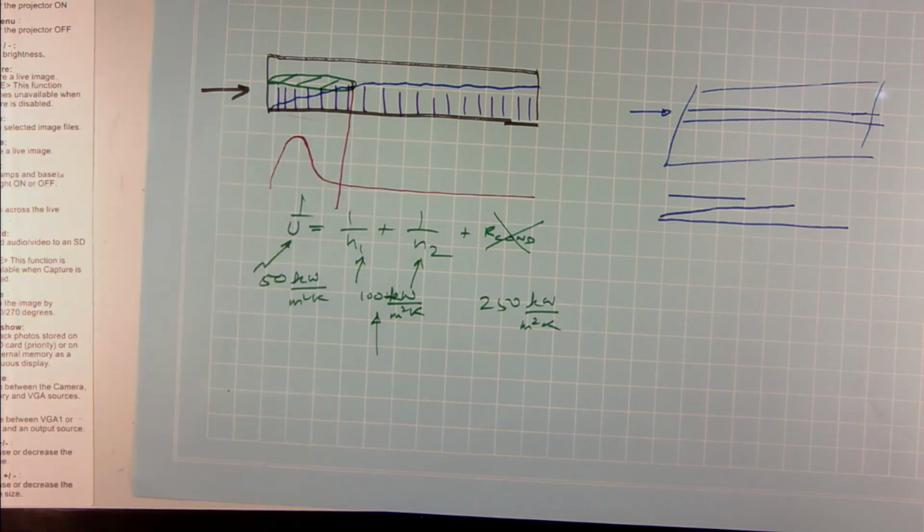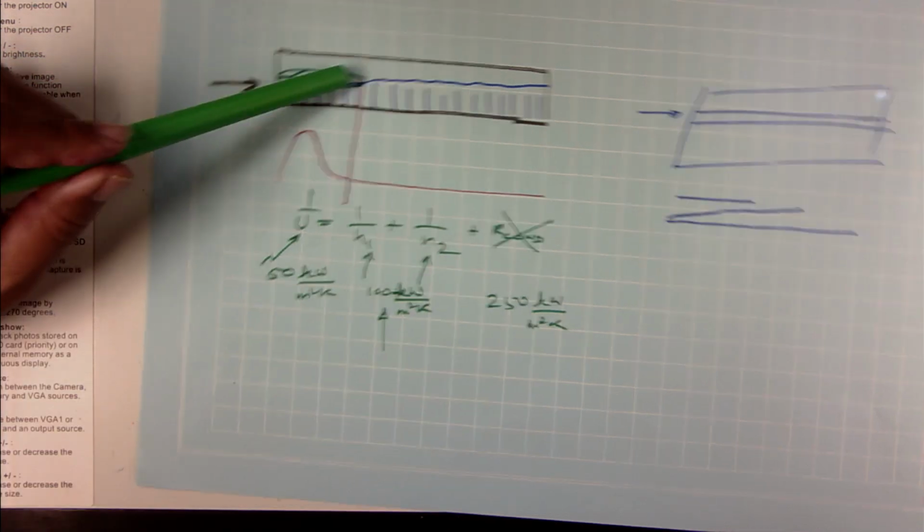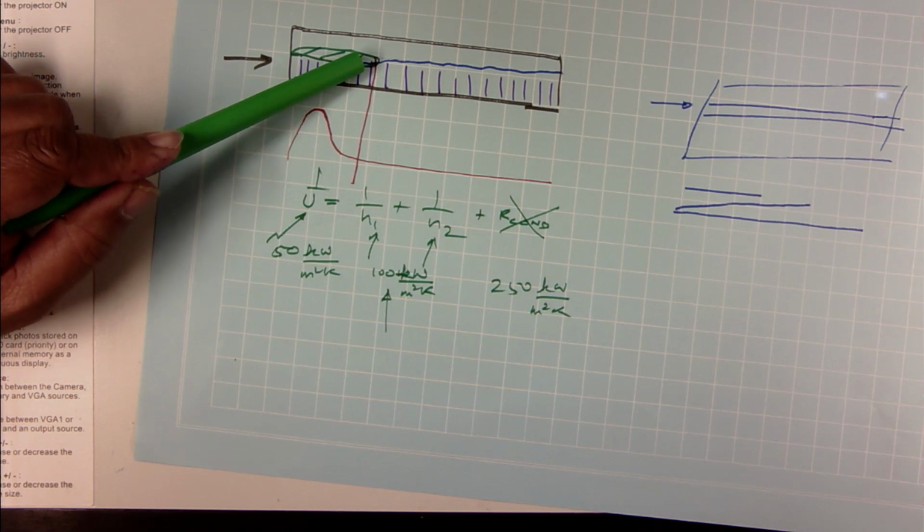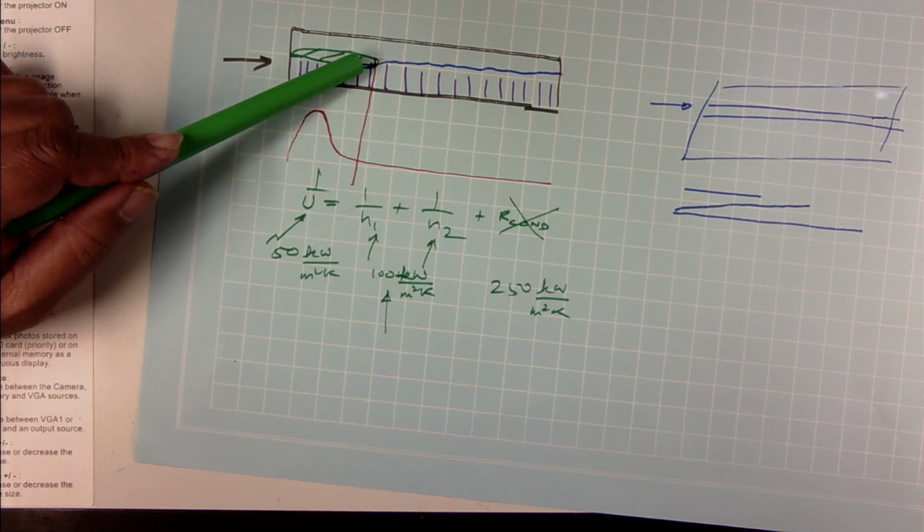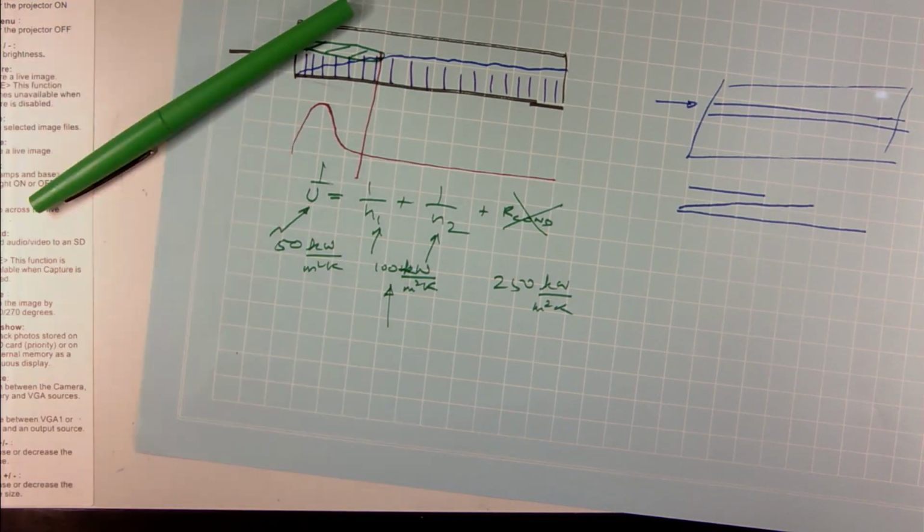Okay. But then we figured the carbon nanotubes were effective only for that first 10% of the heat exchanger. So if you were to redesign the whole thing, instead of making a long heat exchanger, we would make a fat heat exchanger, where the width will be high but the flow direction length will be small.